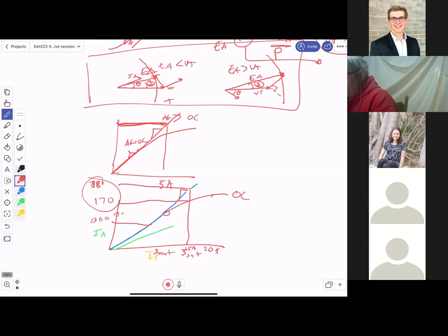So the last thing I think we talked about, remember if it's a motor or a generator, right? We have the efficiency calculation, which is always P out over P in. If it's a generator, P out is electrical, P in is mechanical. If it's a motor, it's the exact opposite. It's still P out over P in, but it's mechanical over electrical. And I think that's it.